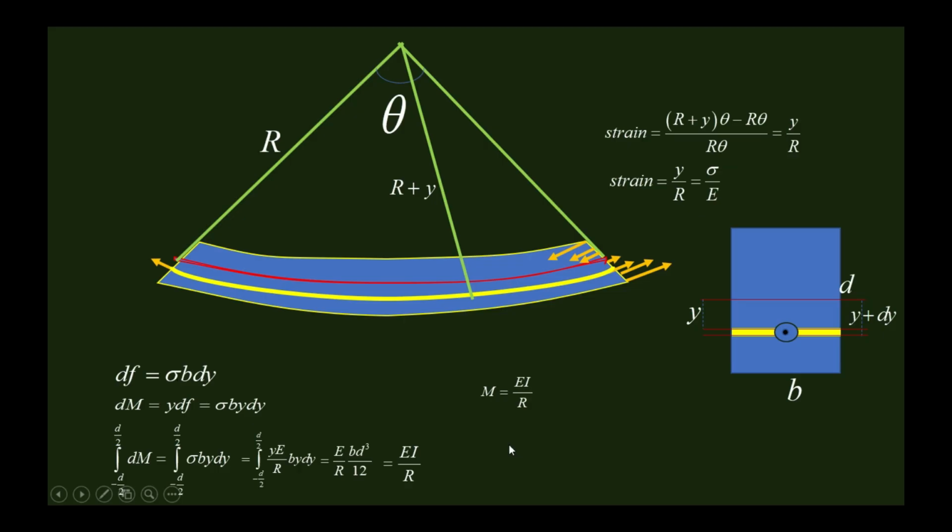In maths, we know that the radius of curvature is given by this expression. Since bending is very small in many cases, the slope of the beam, dy by dx, is very small compared to 1, so we can neglect dy by dx compared to 1. The expression reduces to 1 over the double derivative. This formula you must have studied in maths. So you can use r as 1 over the double derivative of y with respect to x. On the basis of these two formulae, we'll see some questions one by one.